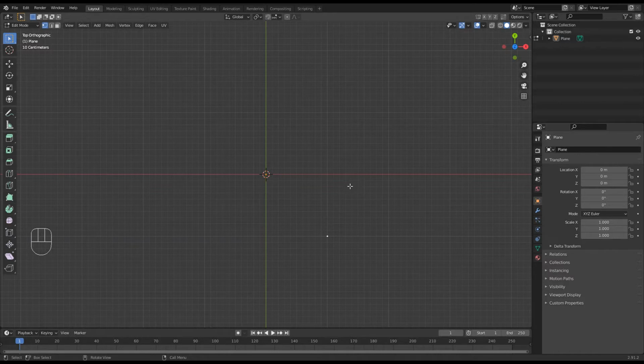So now what one does is hold down the Control key, and then it is a right click, not a left click, but a right click, and a line is built from the first dot to the second. So right click on my mouse, and oops, that one didn't work. There we go. My mouse is a bit suspect, and possibly one more. Okay. Now, if I actually click on top of that one, it won't in fact join it.